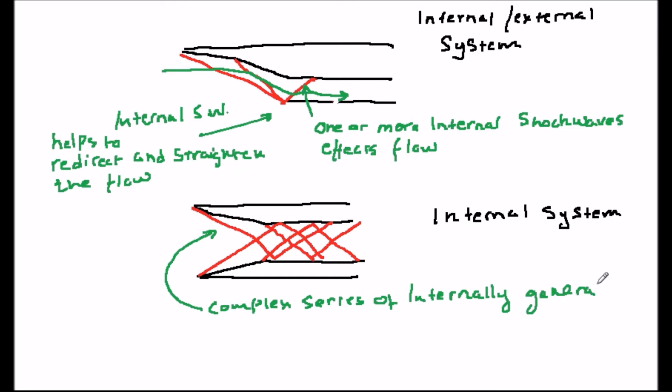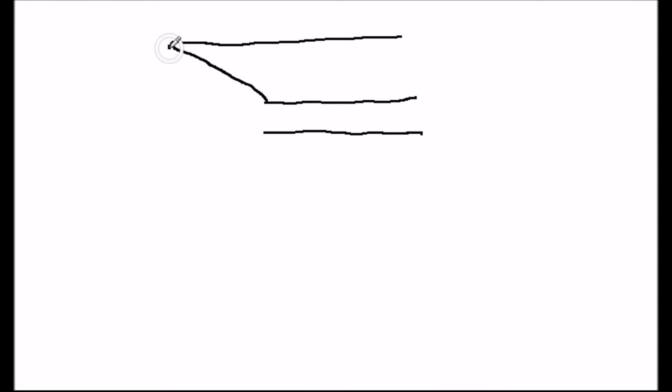One thing should be obvious, however, with a little thought, and that is that it's impossible for any of these intake types to operate efficiently from sea level to the edge of space without an extensive variable geometry type of reshaping of the duct. Now let's have a look at some of the major issues which affect the ducts.